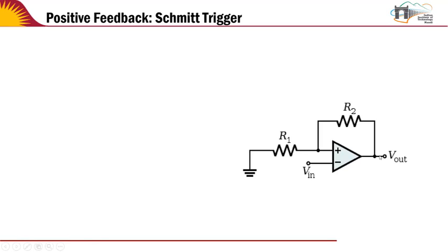In the negative feedback, when the output went back to the negative terminal, the output would always reduce the input difference and ensure that the two inputs V1 and V2 came close to each other. Now this is gone and this has become a positive feedback path.